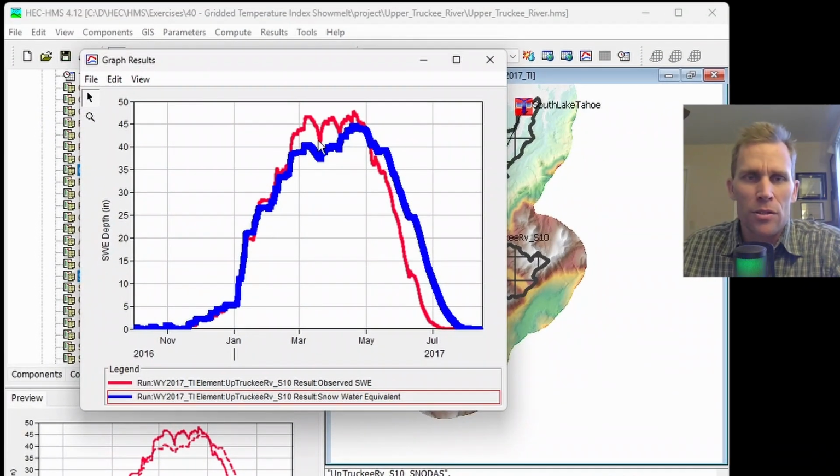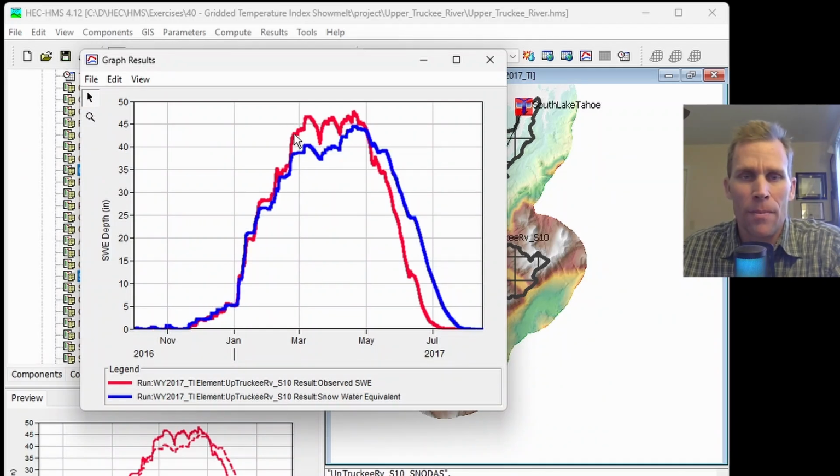The cold rate function: what I want to do is increase the amount of snow we have up here without changing the temperature anymore. We'll keep that at 34. And then after that, we'll deal with the melt rate here, because we have some error happening up here during March, April, and then later in the summer, May, June, July. There's another deviation from computed and observed.